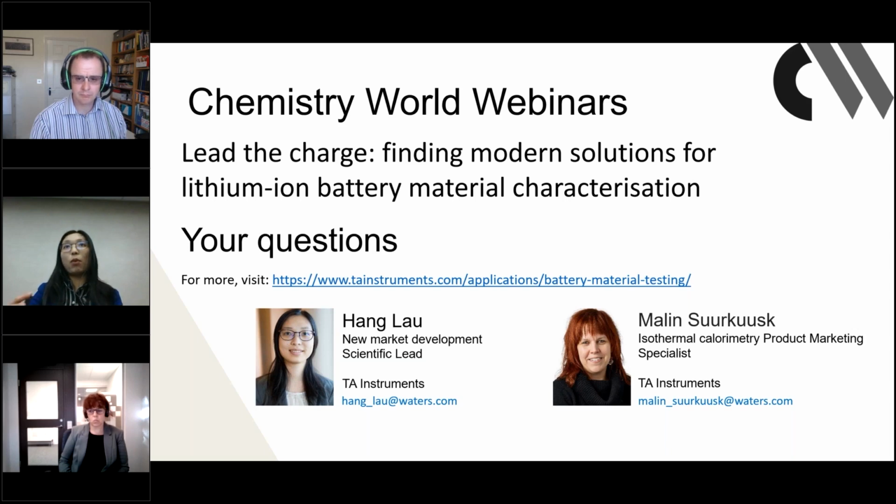The material will expand more. So the thermal expansion coefficient will be different between below the glass transition and above the glass transition. And the TMA allows you to measure those differences and identify the type of phase transition. Depending on the type of transition, you will see slightly different thermal expansion.